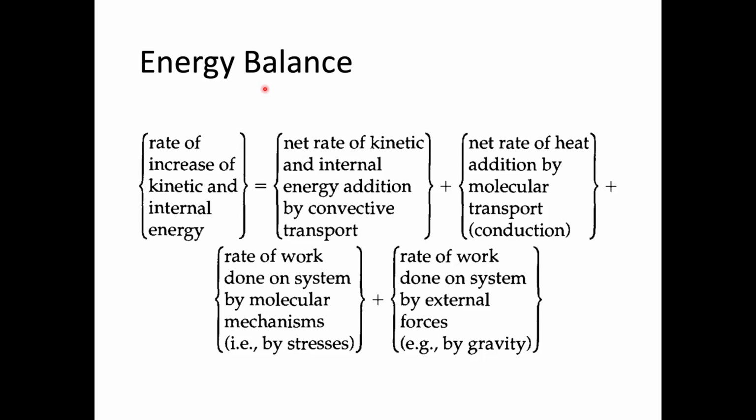In energy balance, we know that the rate of increase of kinetic and internal energy is equal to the net rate of kinetic and internal energy addition by convective transport, and then the net rate of heat addition by molecular transport, which is conduction, and then the rate of work done on the system by molecular mechanisms, for example stress, shear stress or viscosity, and the rate of work done by external forces, for example by gravity.